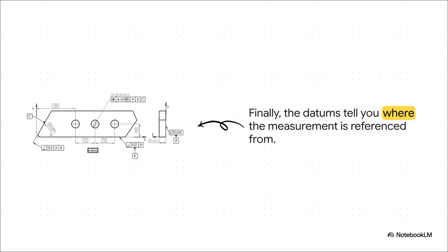And that brings us to the last and maybe most critical piece of the puzzle. The final sections of the frame have letters A, B, and C. These are the datum references. They give us the context. They answer the question, controlled relative to what? Datums are these perfect points, lines, and planes that we anchor our measurements to. Without them, the instruction is basically meaningless.